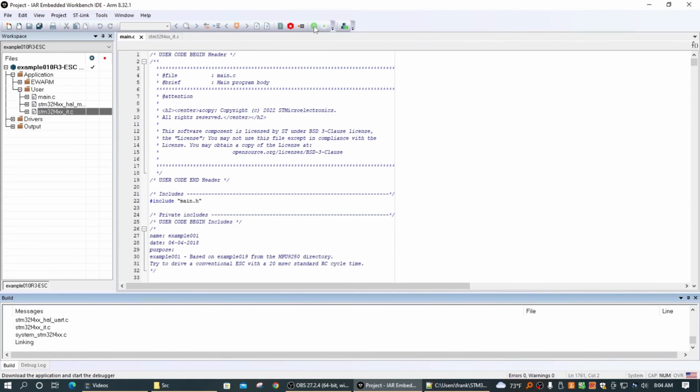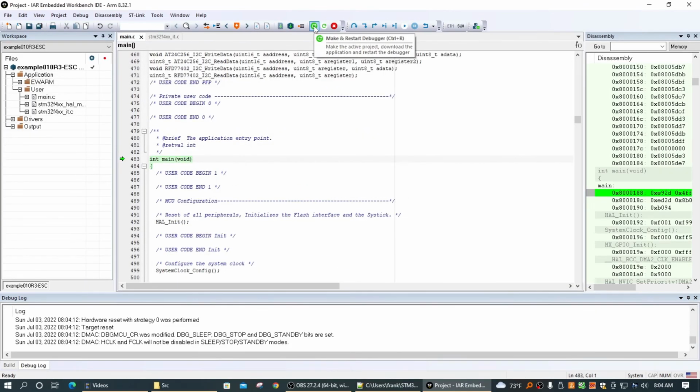So it compiles all these other programs and links them, and these are things that now it's downloading it into the Discovery Board. So we're ready to run. We didn't have any errors. So now I'm going to attempt to run the program, and I do that by pushing this go. So we'll push that, and we'll try to see if there's any signs of life here. And so I believe the processor is running. I could tell by the lights.